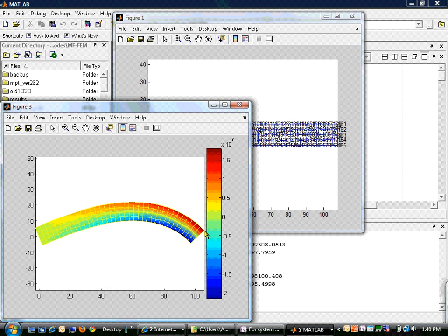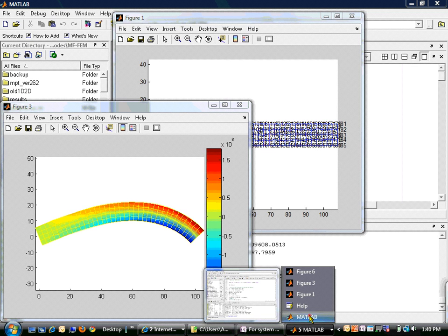So what happens when you apply this bending moment, the beam starts to bend, and at a certain point, the spring here is not able to sustain the load, and at that point you have an instability or buckling. So let's see how that comes about.